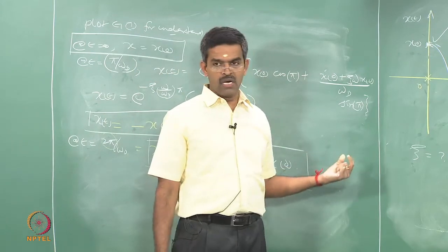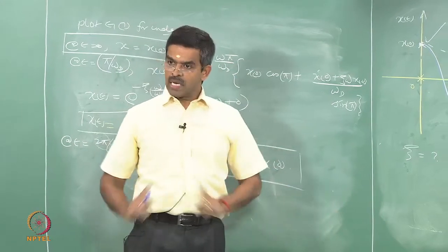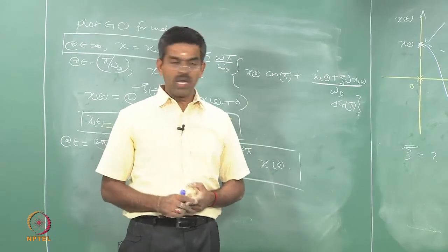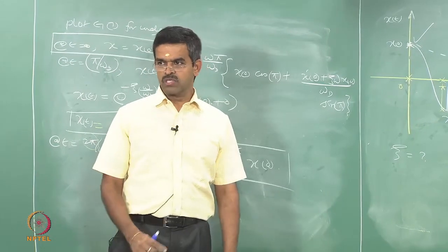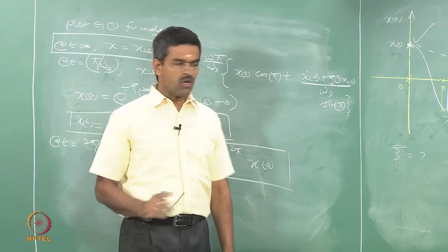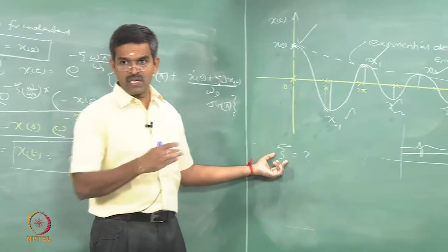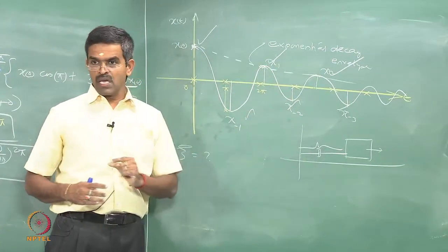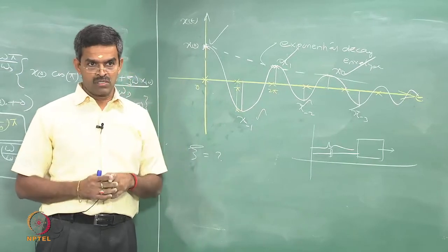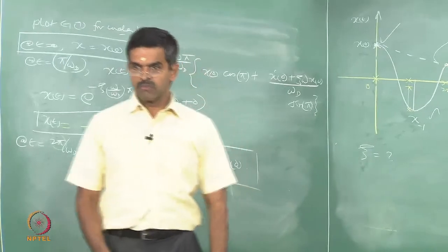Of course, in this lecture we focus viscous damping. In the next lecture we will take up Coulomb damping, compare these two and see why viscous damping is effective and recommended in offshore structures. For sure we have concluded that yes, if you have a damping ratio for any value of zeta, this is exponentially decaying, which is required in the design as a form requirement of offshore structures, what we call as recentering capability of a given system. It must come to 0.